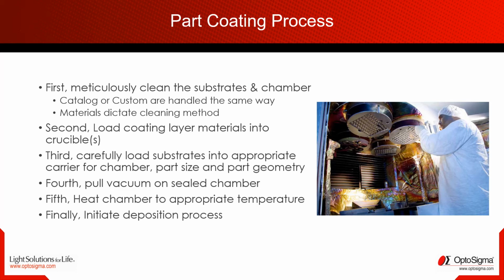The process of getting to depositing material on a substrate is not as trivial as it may seem. There are many important steps. Ensuring the parts are extremely clean before they go into the chamber is critical to avoid chamber contamination, coating adhesion problems, and coating print through from a small particle on the surface. And even the chamber itself has to be thoroughly cleaned, because if it has contamination in it, it may wind up contaminating the optical coating itself and cause failure.